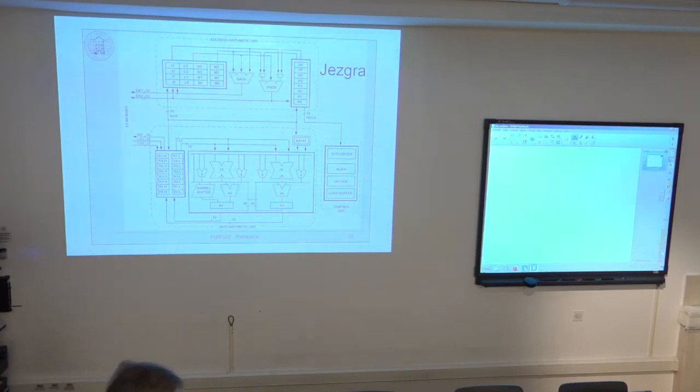As I described previously, with this simple architecture, the base address of the buffer had to be on integer multiple of the first power of 2 greater than the modulus. So for example, if the modulus was 17, then the first larger power of 2 would be 32, and this first address of the buffer must be divisible by 32.